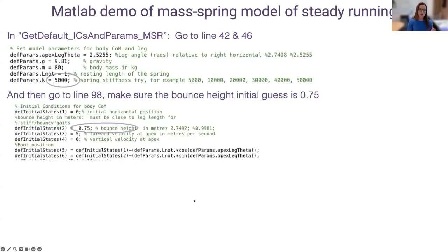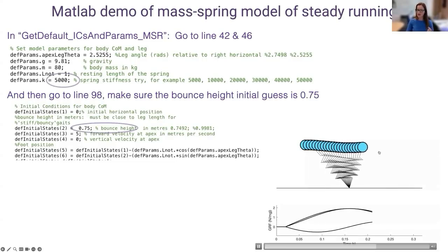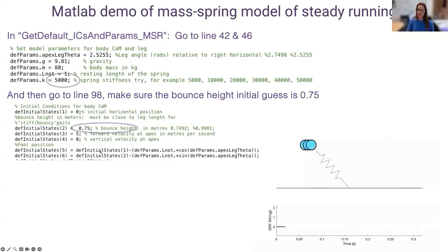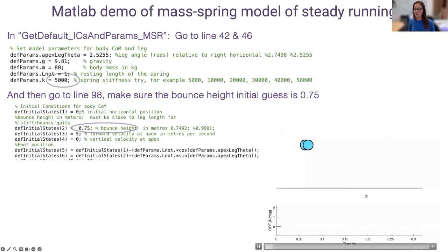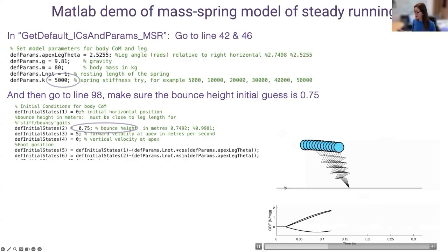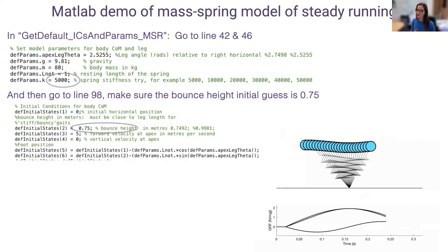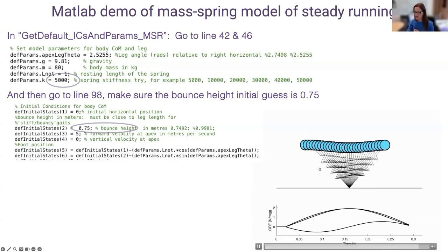Okay. So if you change the parameters, you should get a movie that looks like this. You can see a graph of the ground reaction forces that are modeled. It shows the vertical, fore-aft, and the vector magnitude of the forces. And you can see that the gait has a very long stance phase, right? And a relatively short aerial phase. So this compliant gait has very low bounce height and a relatively smooth motion, right? A relatively long distance traveled during the stance phase.